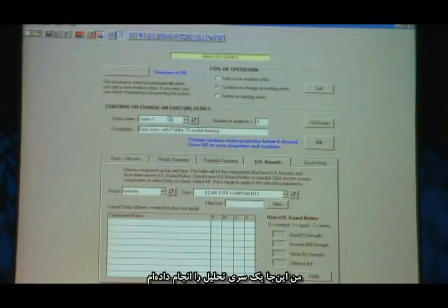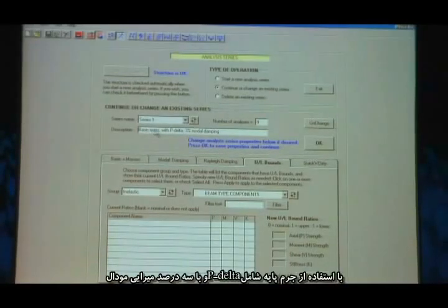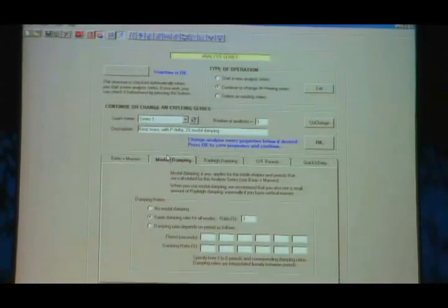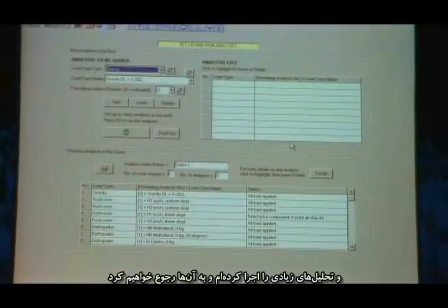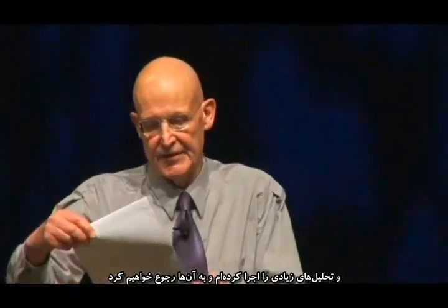I've done just one analysis series here. It uses some basic mass. It includes p-delta, and it's got 3% modal damping. And I've already run a number of analyses.